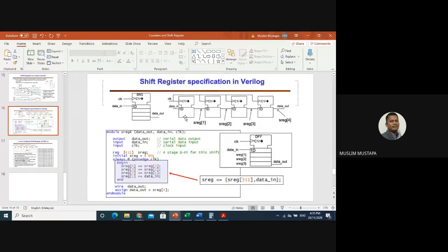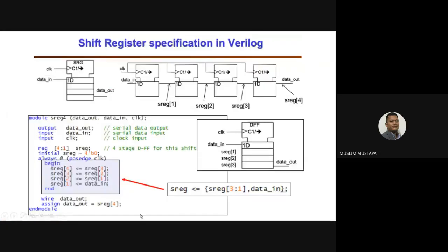So it's going to construct a circuit like this, for example, a shifter. Same thing, if you don't want to use this kind of coding, you just use the symbol of the shifter, shift left or shift right. You don't have to construct all these things, but you are still implementing a shift register. So same circuit, different coding. All right, so that's a kind of tricky question. Any other questions?